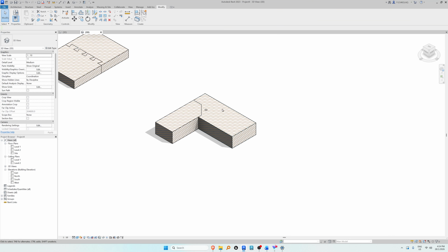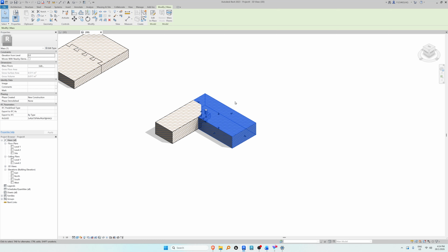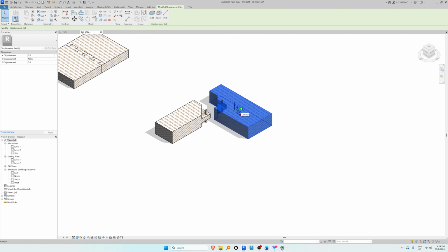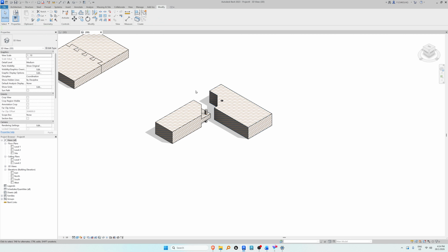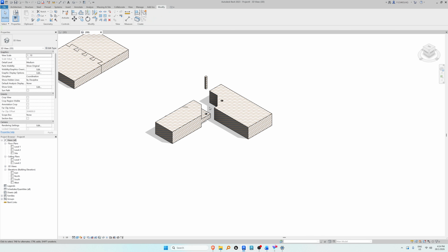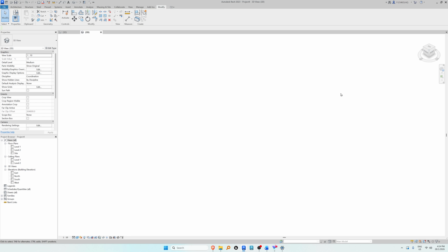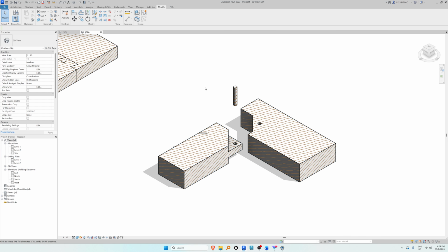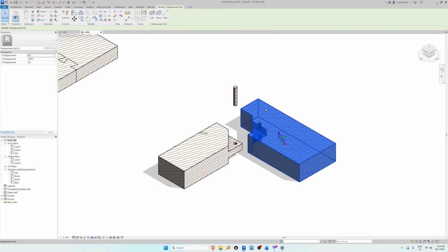For this one, the better displacement to do is pull this to the right. So you pick this, drag this to the right. So you have something like this, and then for your dowel you want to move it up, so all three are visible. Set to your default angle and then pick your displacement lines.